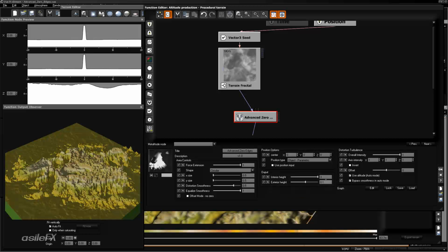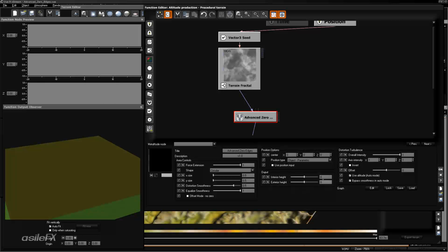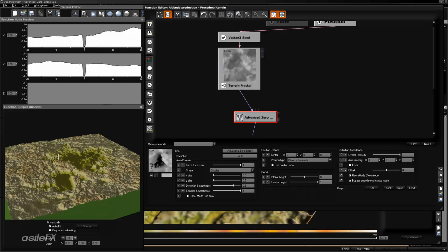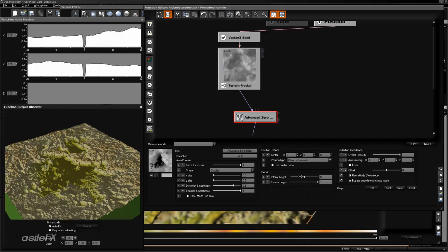With the multiply mode, if you take a look at the output, setting the exterior or the interior to 0 will remove all detail because we're multiplying the terrain by 0. So if we did both by 0, we shouldn't have anything showing. So if we want to subtract the center portion, we could just reverse that. So the interior height is 0 and the exterior is 1.